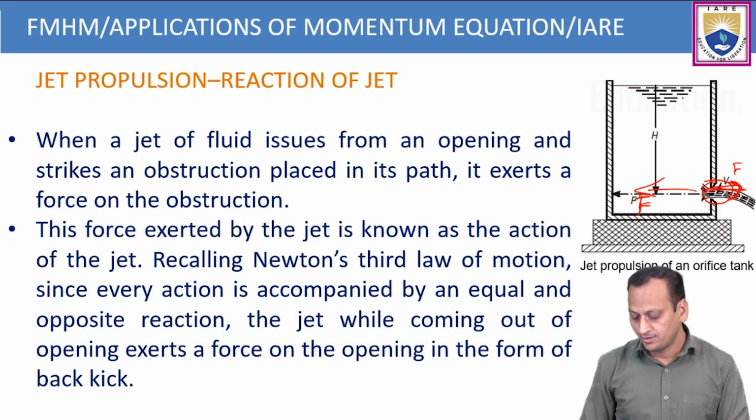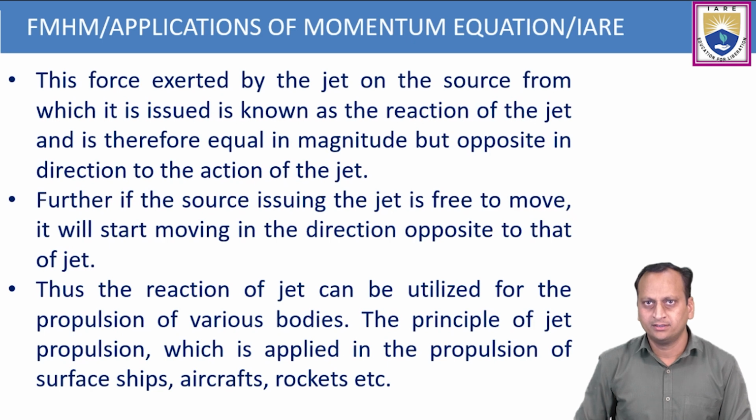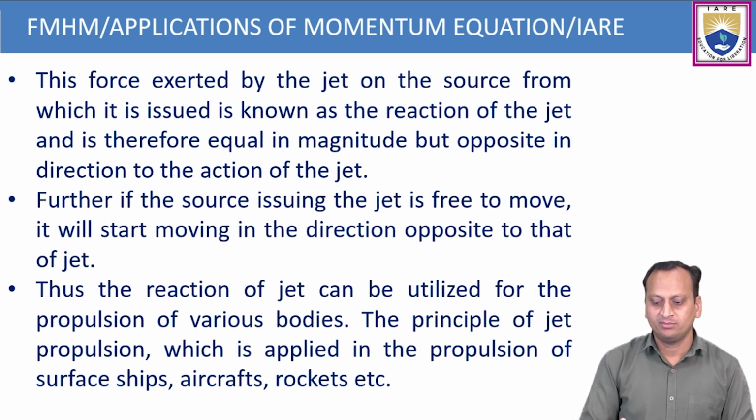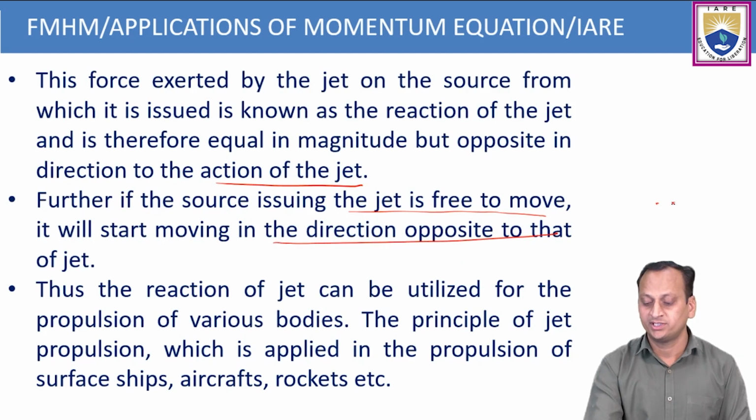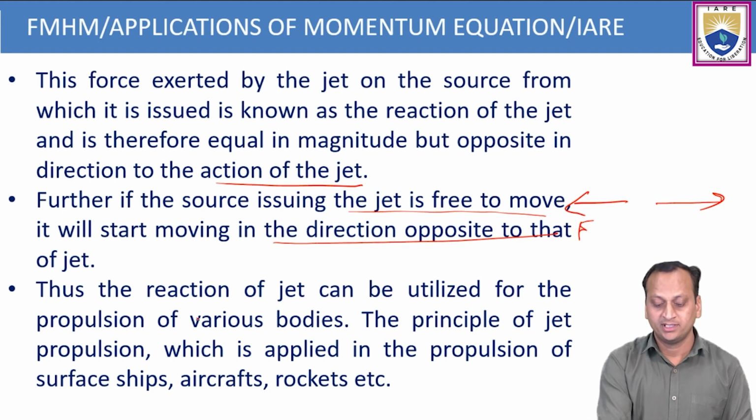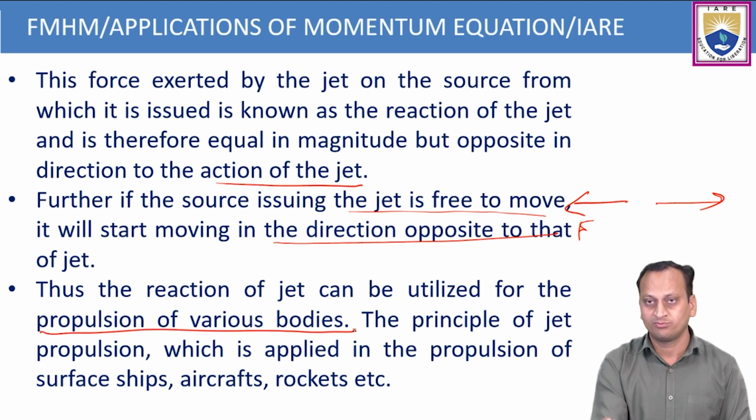So this is another application of impulse momentum: the force exerted by the jet on the source from which it issues is the reaction of the jet, and is therefore equal in magnitude but opposite in direction to the jet. Further, if the source issuing the jet is free to move, it will start moving in the direction opposite to that of the jet. Thus the reaction of a jet can be utilized for the propulsion of various bodies.